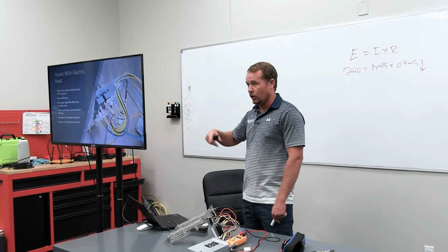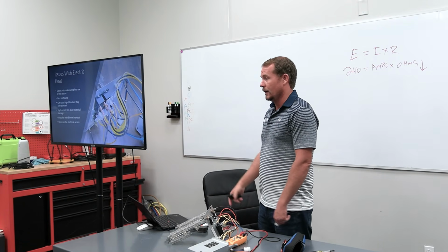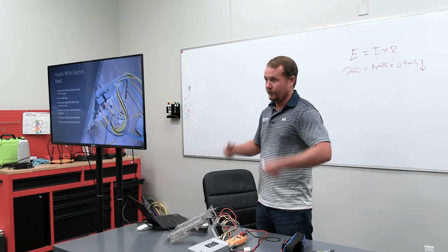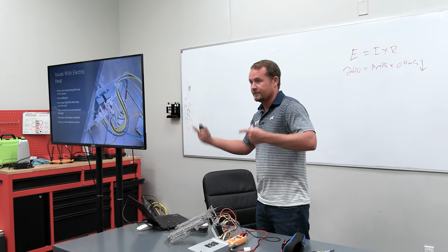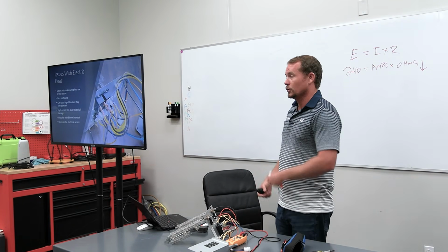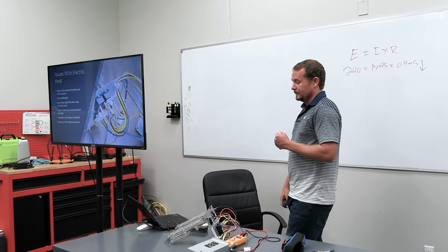And even inspectors aren't often going to blow the whistle and have you stop because they're not going to think about it. It's a change out. They don't think that, oh, you changed out a furnace for a heat pump with heat strips or a straight cool unit with heat strips. Make sense?